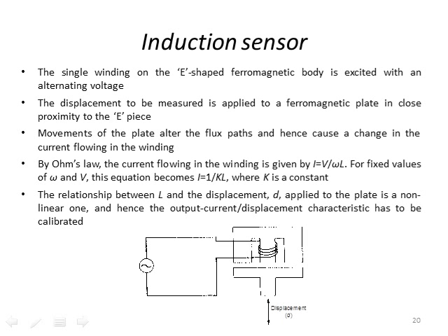So when you have these two ferromagnetic materials, when the displacement is large and the T-shaped material is far away, then the B field that is induced in this material will have a certain configuration. As this T-shaped material is moved closer and the gap is reduced, then the entire circuit changes, and the induced current that you apply or you measure is going to change. So you're just changing how the B field forms in a new geometry, and it causes the flux pattern to change. And then we can measure these.